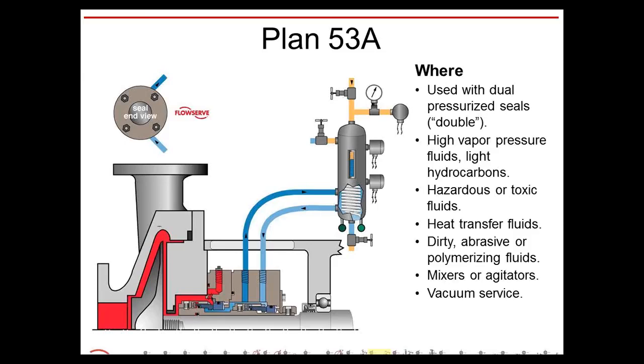Used with, again, dual pressurized seals. Great for light hydrocarbons. Excellent for hazardous or toxic fluids. And it's also very good for dirty and abrasive and polymerizing fluids. Again, you take a lot of that out of things.